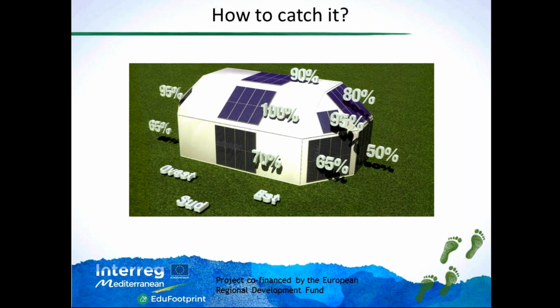But you can see also that if I have to use other areas on the roof or even parts of the facade of the buildings, the loss in terms of energy collected from the sun is not that high. For instance, for these portions of roof on the left and on the right, which are again about 30 degrees tilt but not exactly towards south, the energy loss is just 5%.